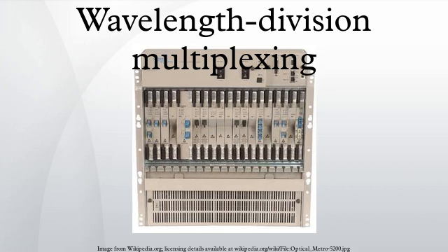The term wavelength-division multiplexing is commonly applied to an optical carrier, whereas frequency-division multiplexing typically applies to a radio carrier. Since wavelength and frequency are tied together through a simple directly inverse relationship, in which the product of frequency and wavelength equals c, the two terms actually describe the same concept.